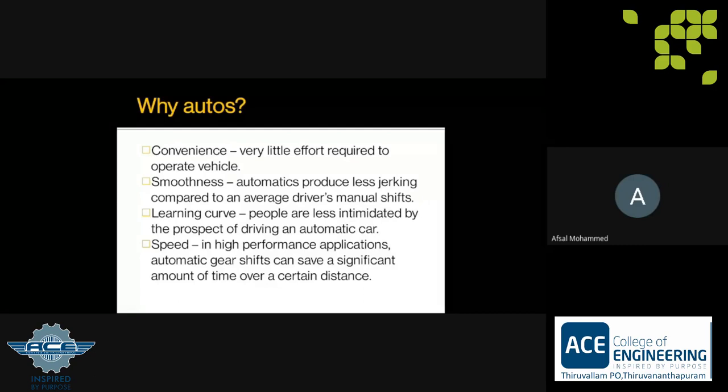This is a point that is of more importance to luxury car owners or people who get their cars driven by somebody else, mainly those who sit in the back seat more than in the driver's seat. Smoothness will ensure maximum comfort because an automatic transmission car will definitely improve on the shift quality. For example, if we shift a manual transmission car, we can feel a jerk or a sudden judder inside the cabin. When we shift from one gear to another, when we press the clutch, the passengers tend to move forward, and when we put the accelerator back on, the passengers will shift their weight backwards. We can eliminate that by reducing the time between shifts, and that is exactly what an automatic transmission does.